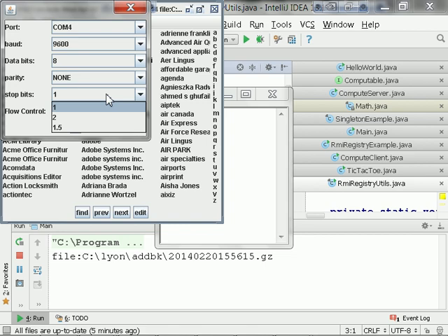what they call a baud rate clock, and that baud rate clock is just like a regular clock with a difference, and the difference is it's got a sample and hold on a phase lock loop. And that sample and hold looks for those framing bits coming in and resynchronizes every time a character comes across so that it can make sure that when there are several zeros in a row, it knows when the bit interval slices have changed. So it has to be able to sample at the center of each one of the bits as they march across the wire.